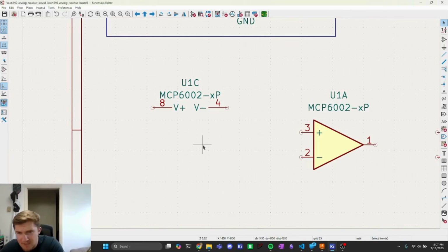Okay, lock in and focus right here. What I'm about to explain is a little bit tricky. This step trips up a lot of people. In order to get the full swing of the AC input signal, we're going to have the center rail for the op amp where its output sits, right? Do not make that ground. A lot of times in our LTSpice schematics, we make that ground, and then we have a plus half voltage, minus half voltage. We're not going to do that here. That's going to make your life tricky and hard and sad. Your ground, we're going to make it the negative rail. Our positive is going to be attached to 3.3.